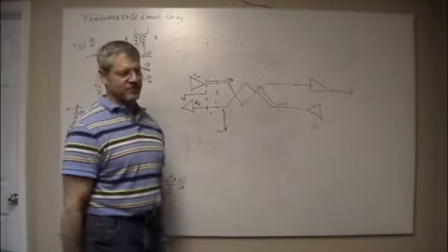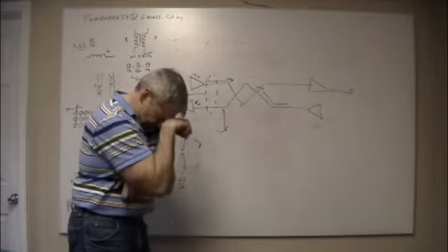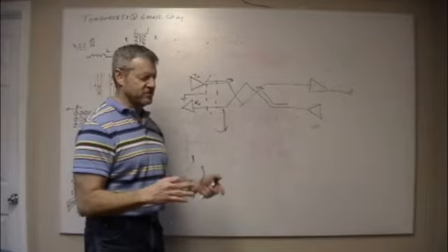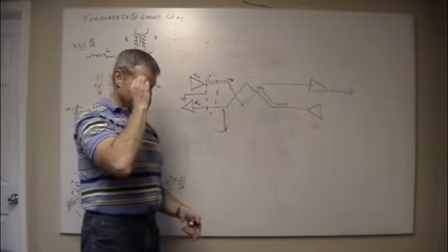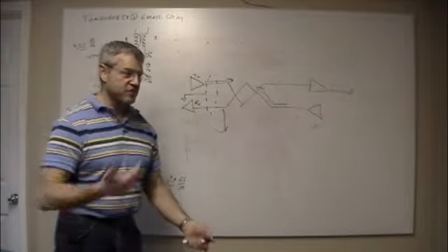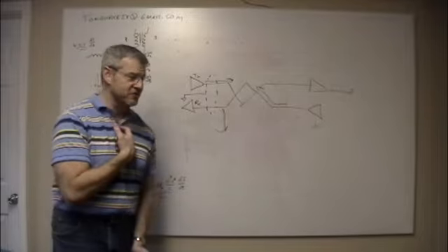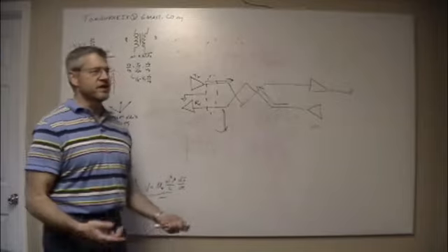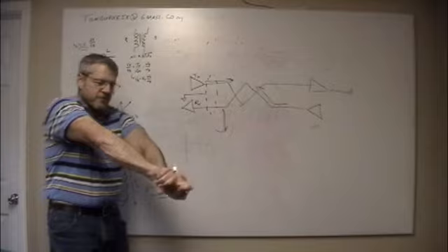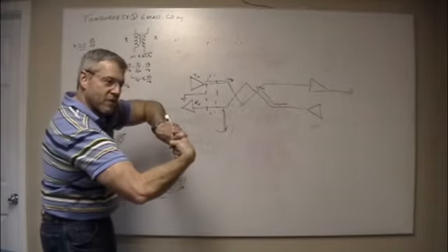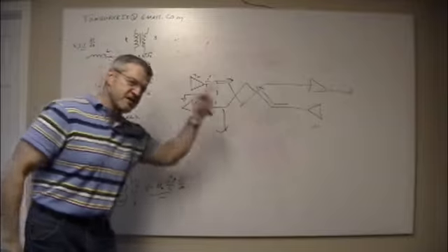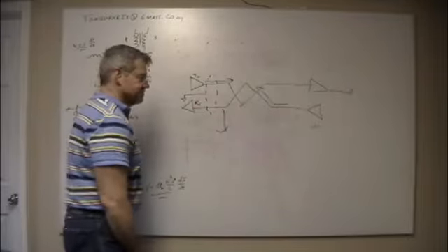And they say, well, we've been doing it for 20 years. I'm like, okay. I understand that you've been doing it, and yes, you can do it, but why do you do it? And so we go through this whole discussion I just had with engineers who are older than me and been doing this a long time. I said, why do you use a twisted pair to get noise down? How does it work? Well, I don't know. And then I end up going through this whole thing with them and saying, this is how a twisted pair works, and what are you doing? You're creating a false signal on your receive every time you transmit. Same on the other end.